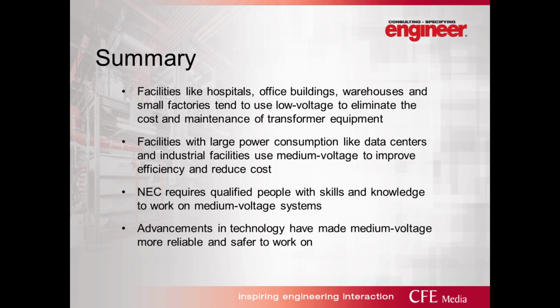We did have a project where we were trying to decide with the client whether they wanted to go medium voltage or low voltage generators. The facility's concern was they could find a person to work on a 480 volt generator relatively quickly, probably 40 people within 20 miles of the facility, whereas if they tried to find a medium voltage qualified person, it may take longer. There may only be one or two in the area. So for them, having medium voltage generators was an issue just because of the people that can work on it. So it is something to think about.